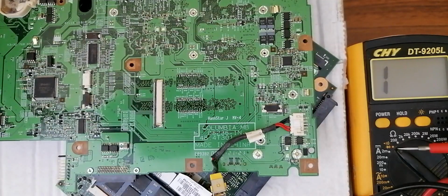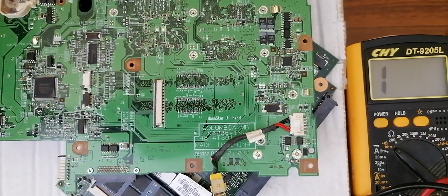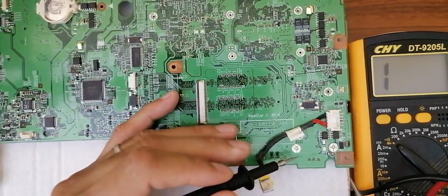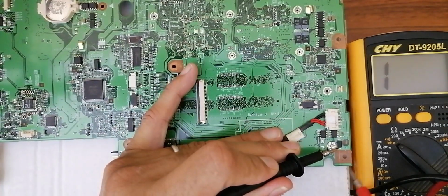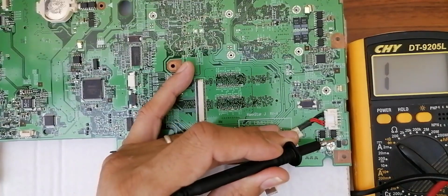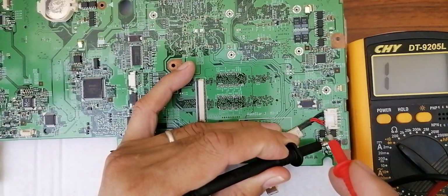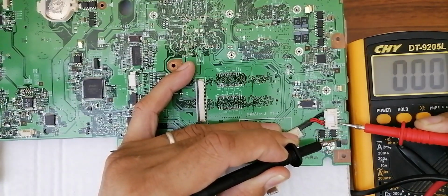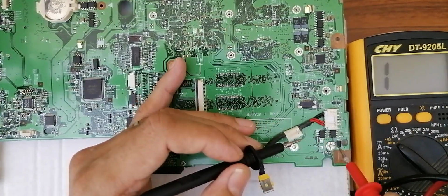So we're gonna select, of course, the continuity option in the multimeter because we're gonna check the continuity. So as I told you, this is the anode. So the anode should be connected to the ground. As you can see in the multimeter, we have 0 reading and buzzer, means the anode is connected to the ground. But the cathode should be connected to the 19 volt power rail, to this red connector. So let's check. As you can see, okay, that's why we call this diode protection diode.